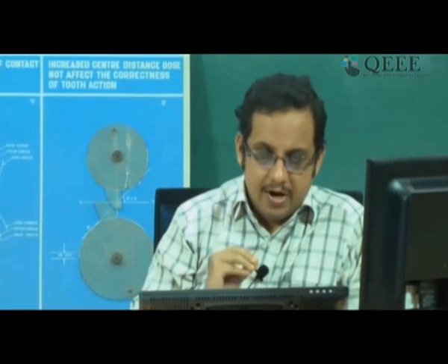So as I said, this mechanism of gearing does not work on the principle of friction, right. It is perfectly permissible to have sliding between the two surfaces, which is why it is a higher pair mechanism. In a higher pair mechanism, you do have sliding as well as rolling without slipping. It is only in a friction disk where we take this approach that there is no slipping possible at the point of contact. But in the case of a gear tooth engagement, if the point of contact is anywhere other than the pitch point, then there is relative slipping between the two gear tooth profiles. I hope I have answered that question for you.